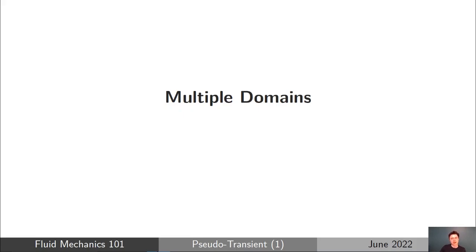So what we've discussed so far is you may have noticed that there's some difference in the speed of the calculation and how long it's going to take, where you could in principle use that true transient approach to get your steady state solution. But what we're trying to do here is we're trying to accelerate and get things in fewer iterations. We want to take as large time steps as possible. We don't really care about converging the simulation properly until right at the end. We're just trying to aggressively step through time to achieve that steady state solution as fast as we can without diverging along the way.